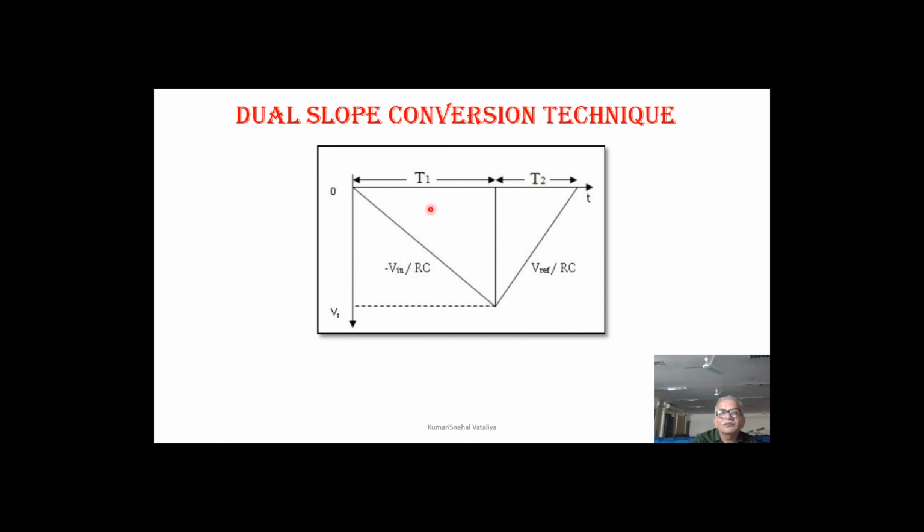And accordingly, T2 will be smaller here, T2 will be larger here, depending upon from which voltage you want to go to 0. And this ramp is generated. These side ramps will be parallel to this, and this side ramps will go up to time T1. Right? And that is how the diagram clearly explains how input is proportional to the digital output produced.